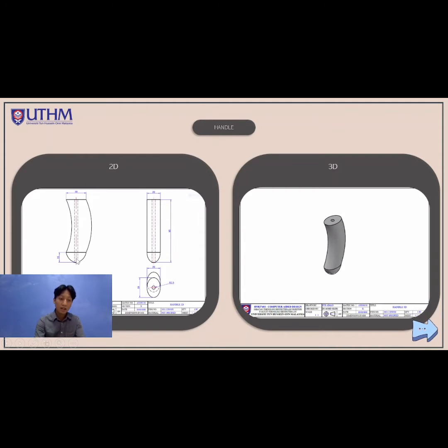And then we make another line using the line command with a length of 10 millimeters on the center of the ellipse, 10 millimeters and 7.5 millimeters from center. And then by using the circle command, we make another circle with radius 2.5 millimeters on the edge of the line. Next we use the loft command to join the circle and the other two ellipses to make the object.